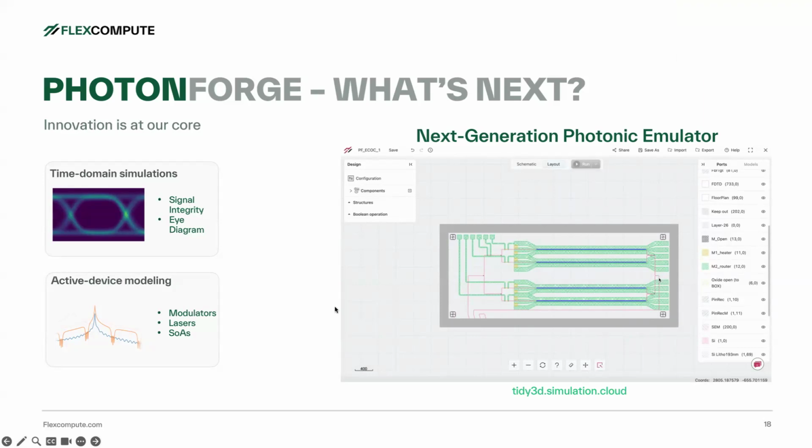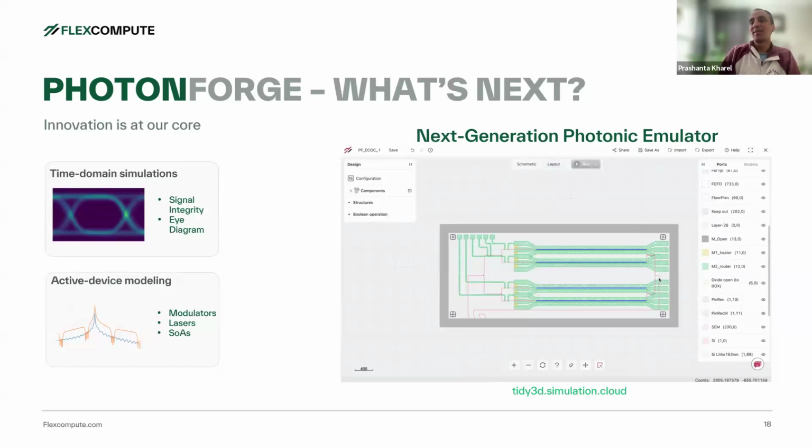Very cool. On the laser part, how do you model the lasers? There are a lot of different ways of doing it. I mean, zeroth order is, especially if you have experimental data, you just load the frequency response and then you use that as an input to your system. More complicated is you start with a rate equation based approach, and then after that you do a 1D traveling wave approach. There's a lot of actual physics to be implemented there, if you want to build more and more accurate models.